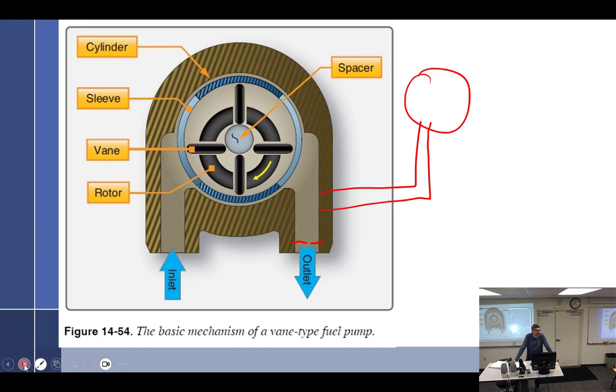So to start these fuel-injected engines, what you have to actually do, and it's kind of crazy, is, everybody does it a little bit differently. I bring the mixture full forward, so we're in what position? Rich. I'll open the throttle up a quarter of the way. Okay, the engine's not running, right? Because we're trying to start it. Everybody's with me? Okay, so mixture rich, throttle part way in.